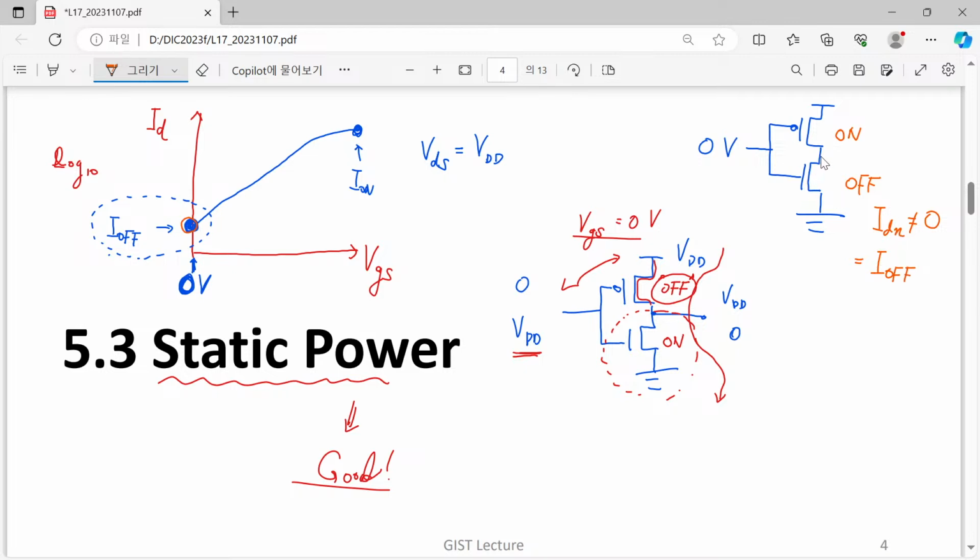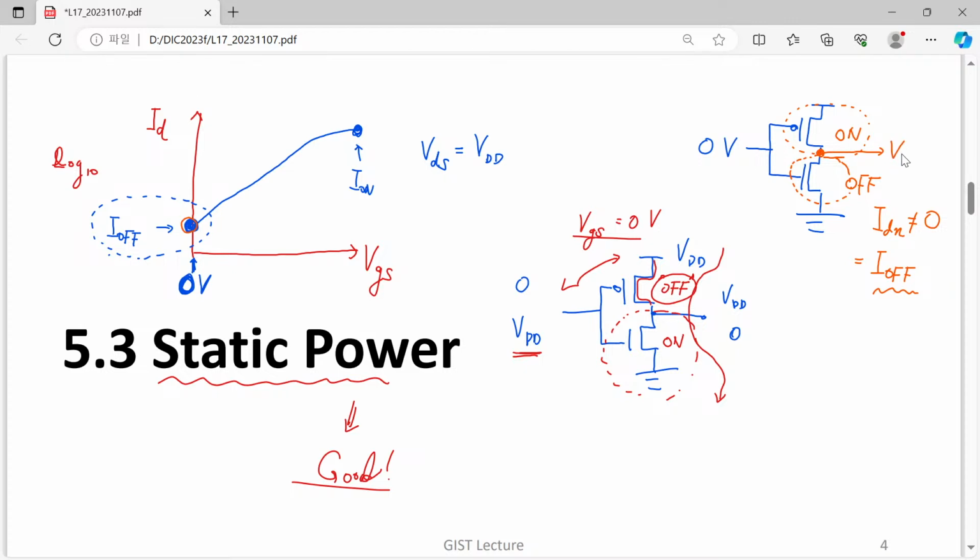So you can easily understand this P MOSFET can drive I off current. Of course, here we have completely turned on P MOSFET, so voltage at this point is slightly adjusted to conduct this I off current even in the case of our P MOSFET. For P MOSFET, conducting this small amount of current doesn't matter because it is already fully turned on.